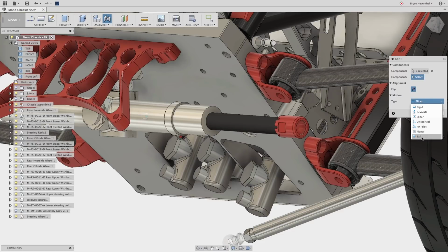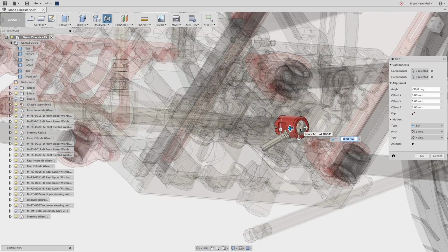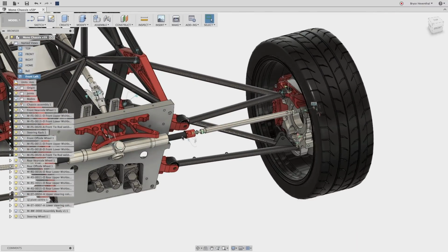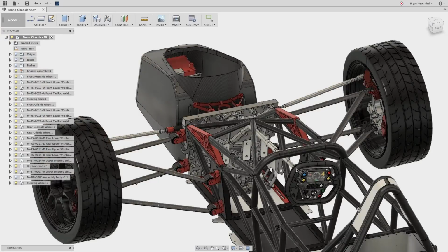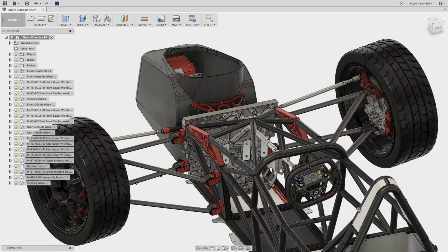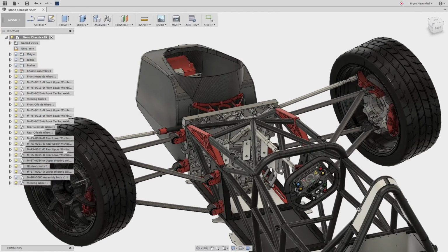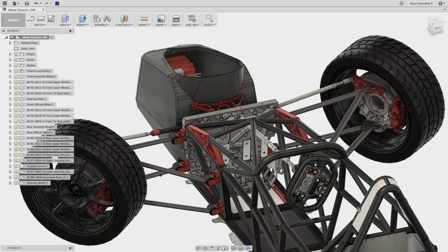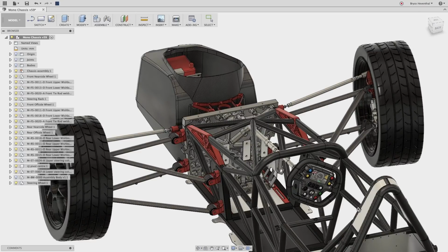Joints describe the mechanism in the form of rigid, revolute, slider, cylindrical, pin slot, planar, and ball. Each part in an assembly has a working relationship with it. Components have range of motion, hard limits, relationships, and cause and effect. Yet joints serve the purpose of positioning components relative to one another, but with the intelligence you've asked for.